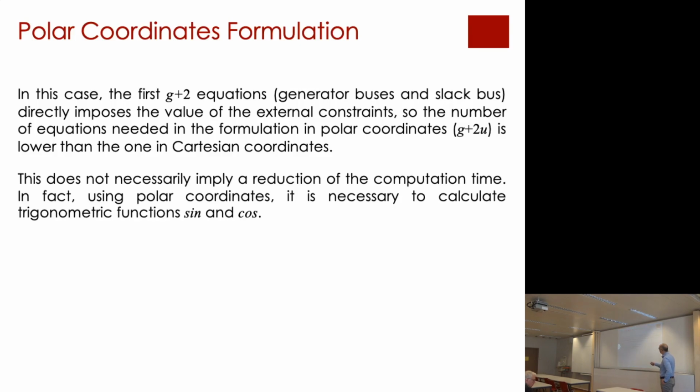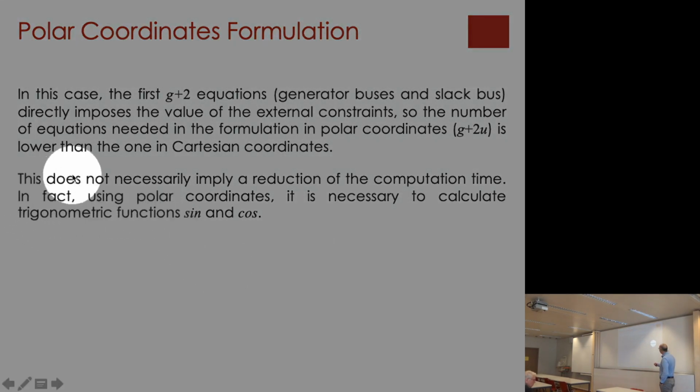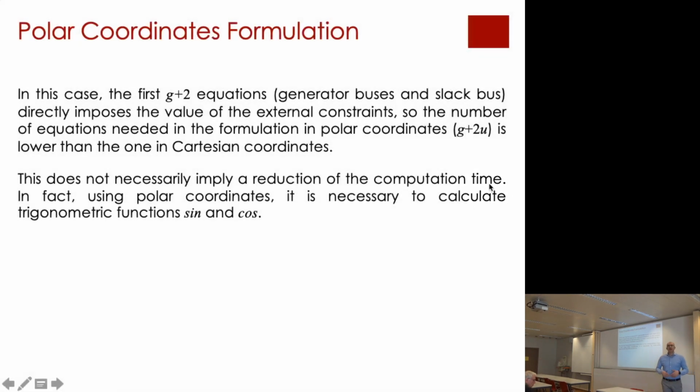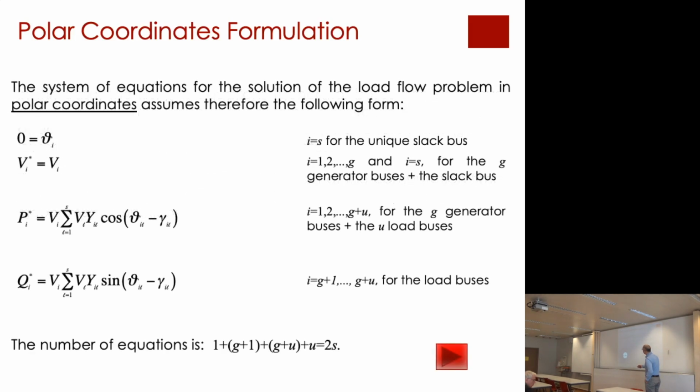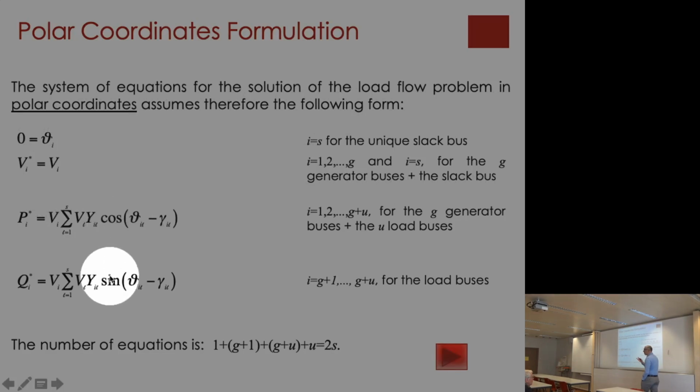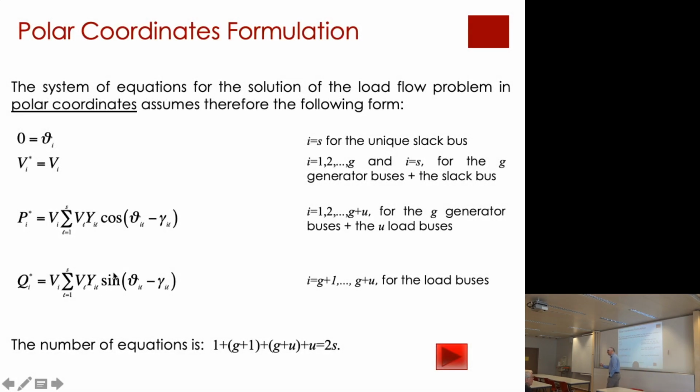However, this does not necessarily imply, as is written here, that a reduction of the computational time is associated to the polar coordinate formulation. This is because the equalities that you get for the active and reactive powers contain trigonometric functions that may exhibit more difficulties to converge.